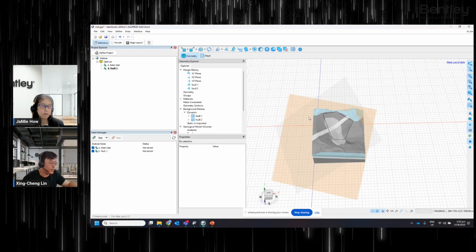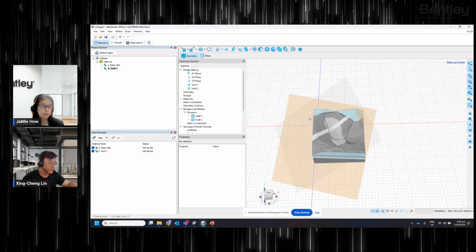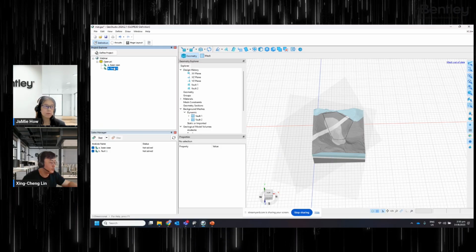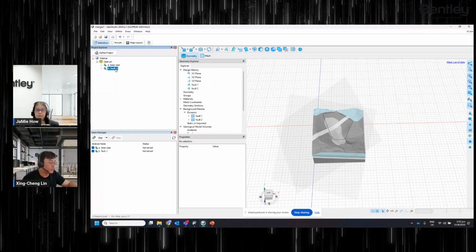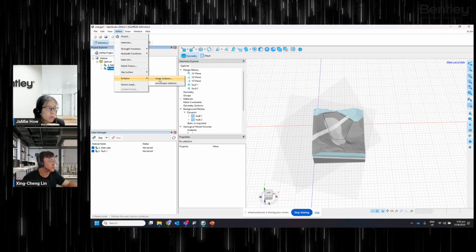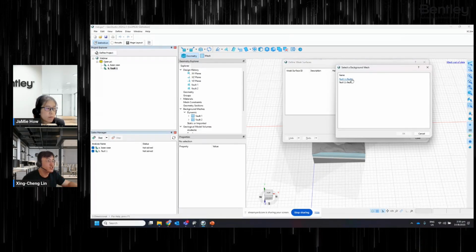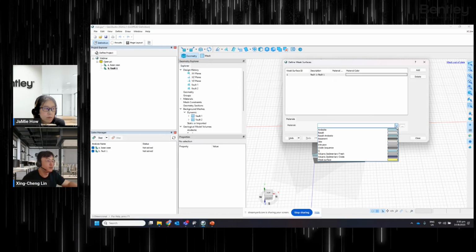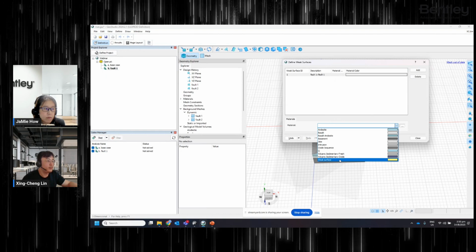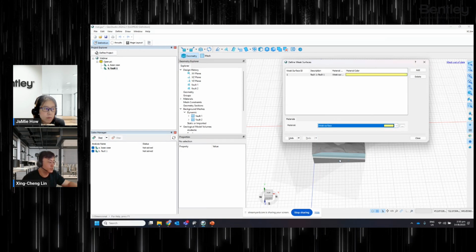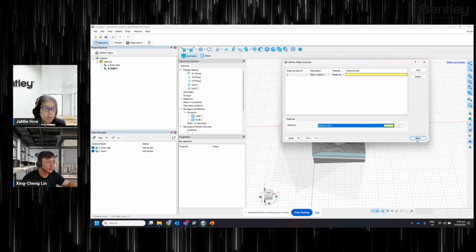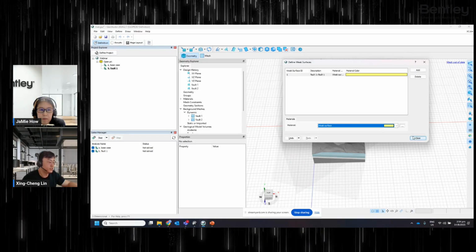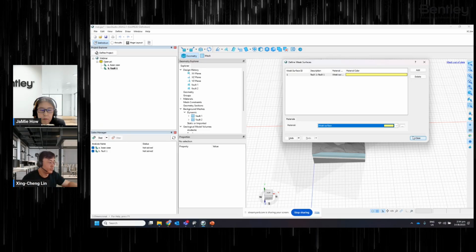Once you have the background mesh in place, the next thing you do is to create a weak layer. So you are working in case number two, which is fault one, with just fault one active. I therefore navigate to define weak surface. I'm going to add a background mesh representing fault number one. And down here, I'm going to click on the button to choose the correct material type representing the weak surfaces. Once you see the color change, that means the setting has been done correctly. So now the material has been correctly associated with this particular weak plane for fault number one.